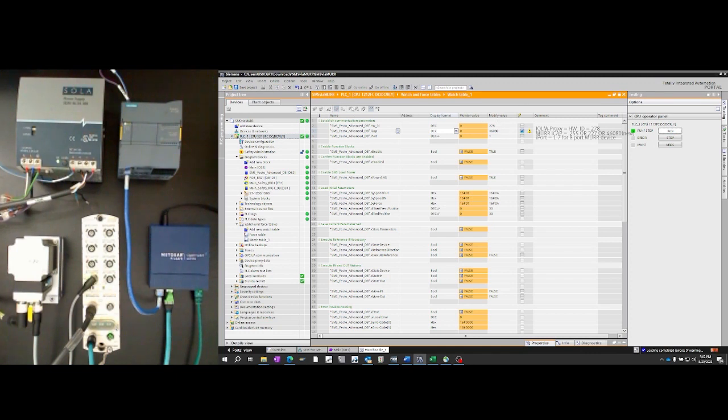Next, from my watch table, I'll preload the communication parameter information as well as enable communication from the block. Now you can see we're starting to get a little bit more information. The next thing I'll do is confirm that my function block is enabled, which it is. Next, I'll supply load power, and you'll hear a small hum occur on the drive if you're paying attention.